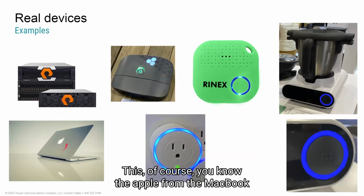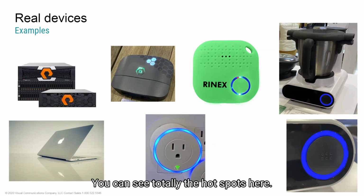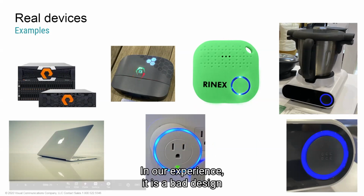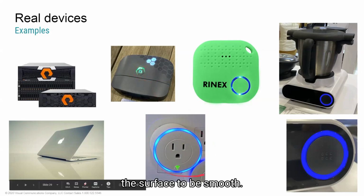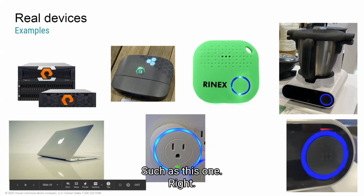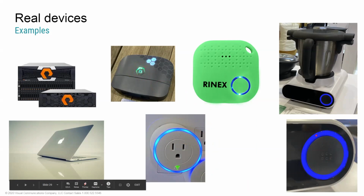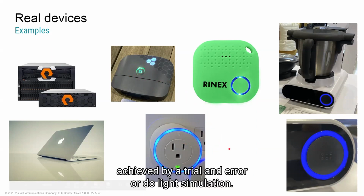These, of course, the Apple ones from the MacBooks, are pretty neat. But look at these guys. You can see the hotspots totally here. So, I mean, if that's your design intent, okay. But in our experience, this is a bad design. You want the light pipe surface to be smooth, such as this one, right? You can see that the light ring is perfectly even all around, and this is something that can only be achieved by trial and error, or by doing a light simulation.